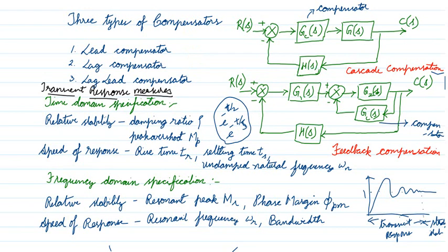As I discussed earlier, two types of performance measures can be given. One is the transient response, another is the steady state response. If you look at the second order underdamped system unit step response, it will be oscillating as well as exponentially decaying. Where it is oscillating is temporary, for a very little time. That response is called transient response. Permanently it is going to settle at 1. Such response is called steady state response. So the complete response is nothing but transient response plus steady state response.